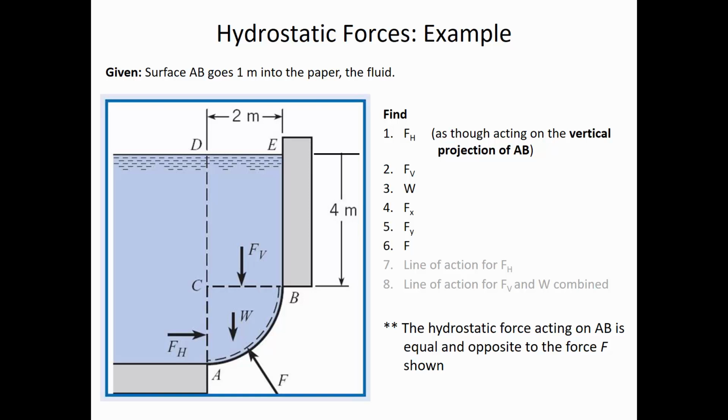So we've got a gate here that's vertically oriented, which is nice. Here's the centroid. We previously determined that the centroid delta H is 5 meters down to where that force is located. What we're asking is this horizontal force component, F sub H, what is its location? And we know that's YCP. YCP is the depth to the center of pressure. That's what CP stands for.